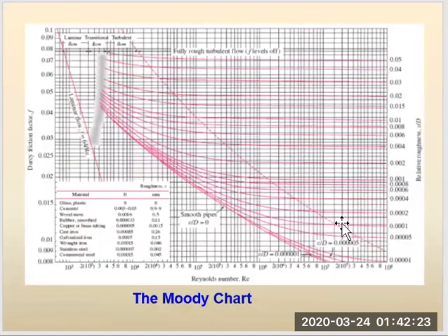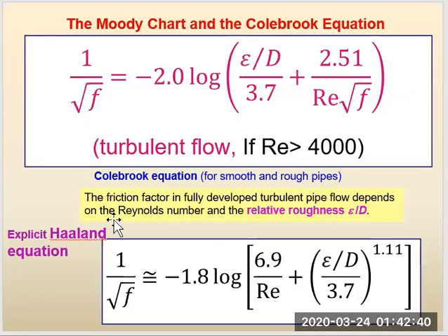This is a more detailed or actual form of the Moody diagram. So you can use the Moody diagram to calculate your friction factor for turbulent or laminar flow. But since you already have access to the formula, the correlation is really easier to calculate. So just use these equations, or 64 over Reynolds number if you have laminar flow.